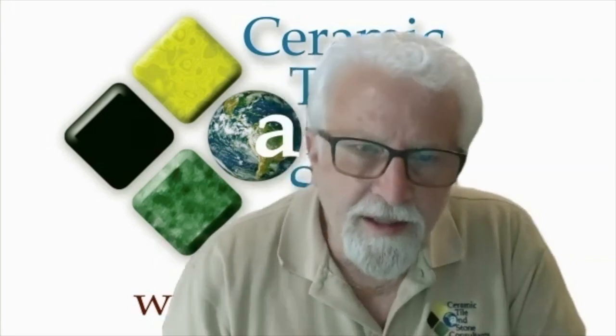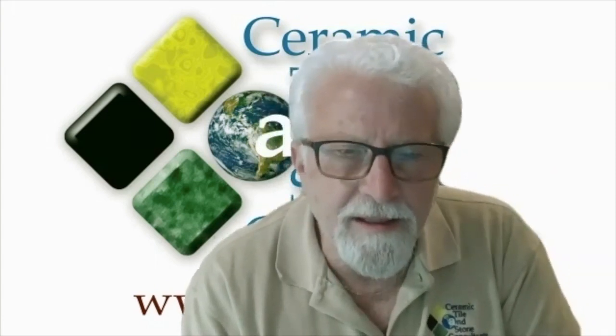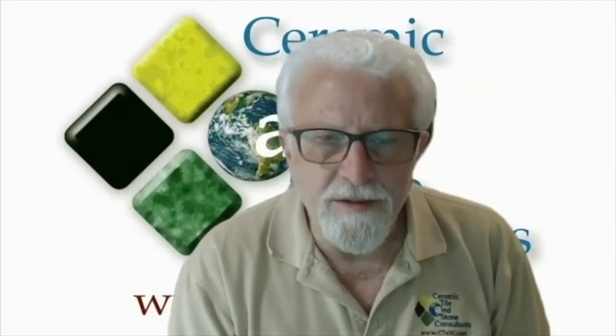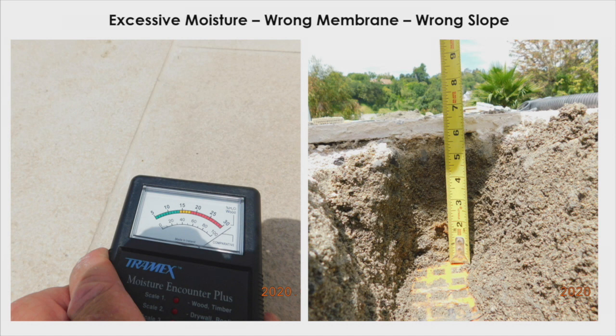We started doing some destructive testing, and one of the things that I always say is that when there's a problem, it's never due to one deficiency. Generally speaking, it's due to multiple compounding deficiencies that leads to a failure. So here you can see you got over 5 inches of mortar bed here, and plus the mortar bed had a high content of sand to cement, and was very porous, and so that becomes like a sponge.